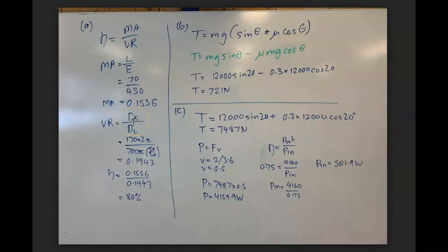Okay, so what is the distance traveled by the pedal, right? So the distance traveled by the pedal where the human is applying their effort. Well, we know that the radius is 170, so the circumference is going to be 170 times 2 times pi. The distance traveled by the big wheel, they've given us a diameter, so the circumference is going to be 700 pi. However, the big wheel is going to spin around at a ratio of 2.5 times. The big wheel is going to turn around 2.5 times for every time the pedal turns around.